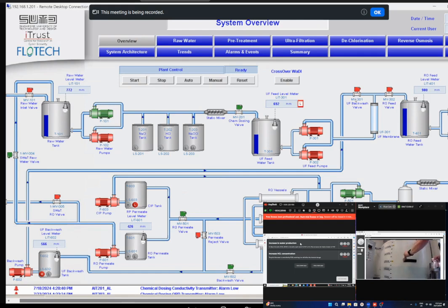The other is direct access from inside the plant, and that would be an access for an insider. And the third one is a mix of insider and remote access, which could happen when there's a contractor that comes into the plant and on purpose or by mistake, the contractor attaches the laptop to the plant and a malware is injected into the plant computers, and that malware somehow allows an internet connection between the plant and an adversary.